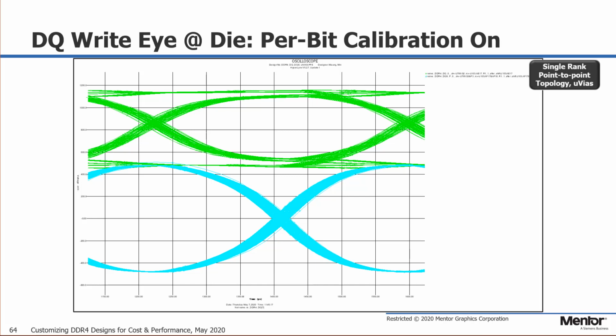At the end of the day, we care about the timing at the die the most. So if it is failing the margins at the die but passing at the pin, then it could be that the package models are not accurate, or the simulator had some issues with the modeling of the package, or the package is not optimized. In that case, you should contact the vendor to see if the results make sense.